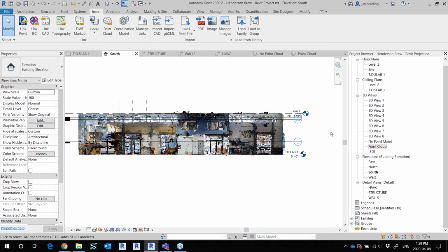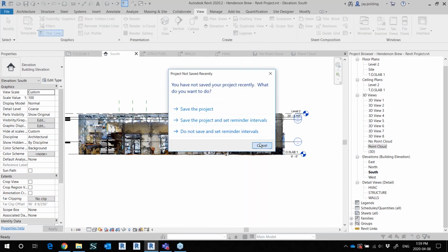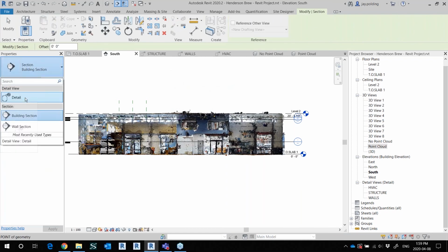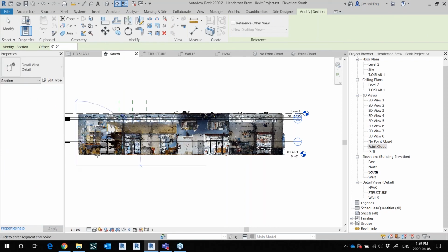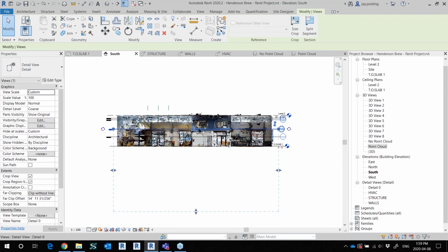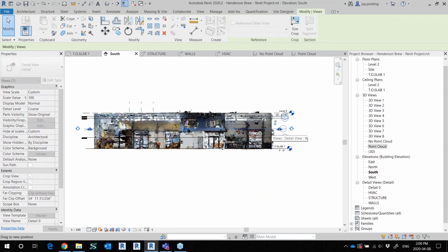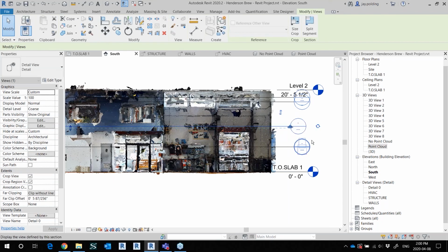We've got levels. Next step is, and Dan and I were talking about this, sort of what we call a pro tip. So if you're in Revit, you can make something called a detail section. It's right here. It's just a type of section. You go to the type selector here and choose detail. The reason why you use detail is because you can go at any angle in any view. So what angle do I want? I think I just want this angle right here. And I'm going to change the depth of that section. I just say, pay really good attention to this tip that Jay is going through.